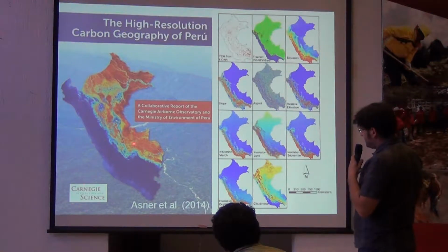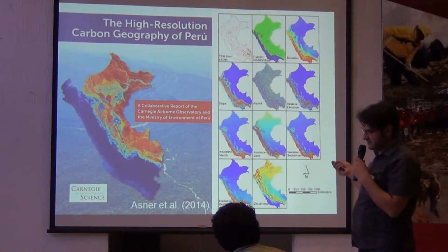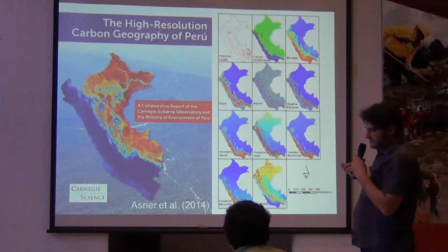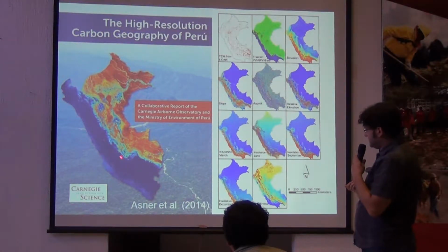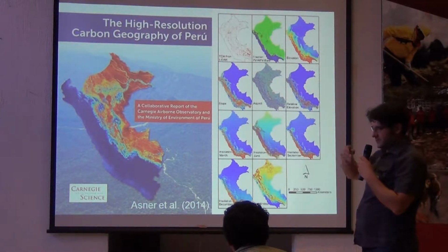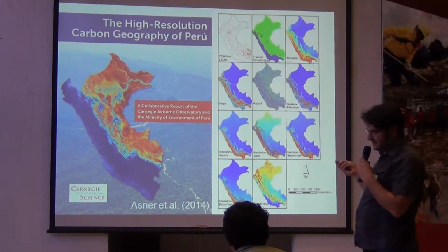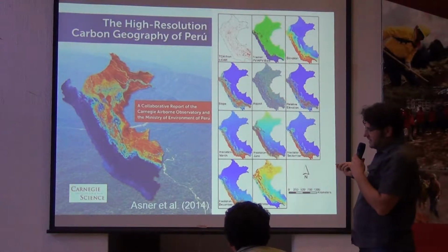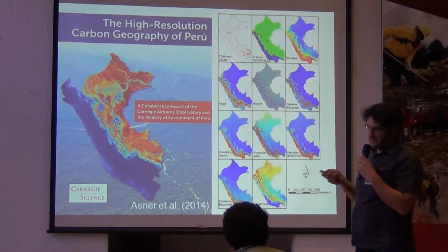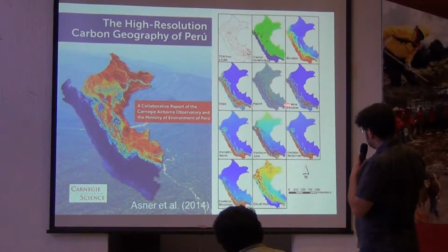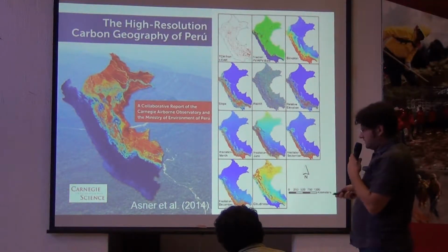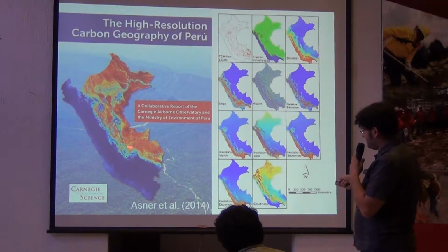Typically, we have to calibrate models that relate whatever the sensor measures to the biomass on the ground. And for that, we need quite a large sample of field measurements. In Peru, for instance, in contrast to Mexico, this is not available. So they used airborne laser scanners in a 2-stage upsampling approach. Few field measurements calibrate models that relate the LiDAR measurements to biomass, and then the LiDAR can help to calibrate models that relate the Landsat data, and also some additional information on the elevation and the general geography of the area, to biomass. And that's how they produced the biomass map for Peru.